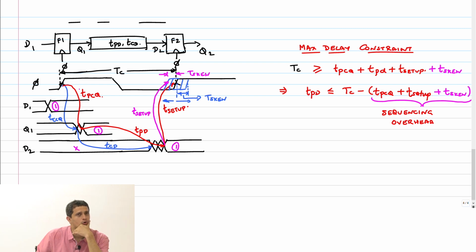So the question is, should you count it twice or not? Exactly. It's just a question of which one you take as a reference, that's all. And T skew just boils down to what you define as T skew, right? That worst case number is with respect to one reference clock, where do these edges move.